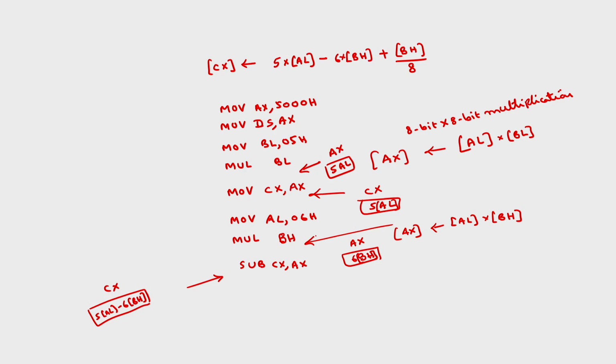For example, if I take 100 which is 4, and shift this to the right by 1 bit position, what happens? This is 010 which is 2, this is equal to 4 by 2. If I shift one more bit, 001, this is 1 which is 4 by 4.